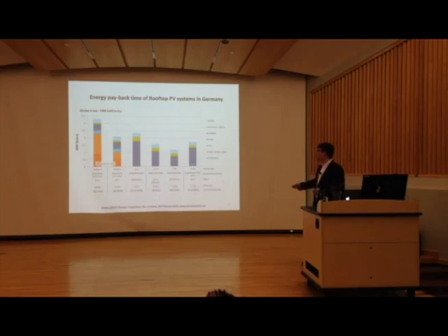Of course, it depends on different technologies like silicon, also amorphous silicon, polysilicon, cadmium telluride, CIGS. Although efficiency-wise all these technologies are pretty close, from 16 to 20%, the energy involved in production is a bit different, so that's why energy payback time is different. If you look at this, single crystal silicon is not that good, although it gives the best efficiency. Energy payback time is a bit more than 3 years.